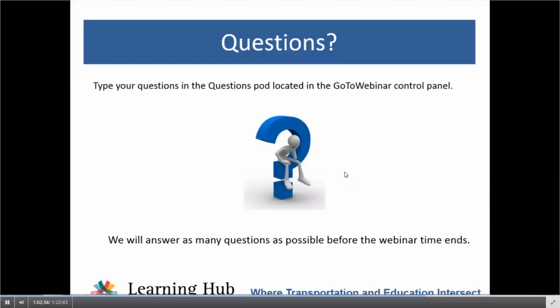What we do recommend is that whenever you have local data available, you use that, and the guide does provide information on developing local default values. So if you have information on local signal timing, for example, that would be something that the guide would recommend you use in favor of the national default values provided in the HCM.